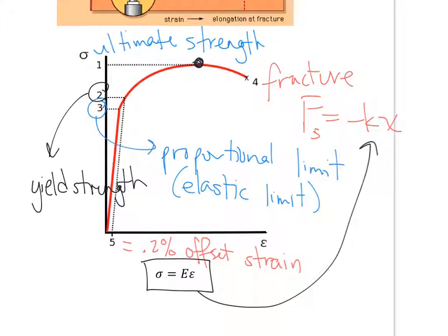So this, take a look. What do we say? This was the 0.2% off yield. So look, if we move this over to be a percentage, it's going to be 0.2%. This means that 0.2% of this has stretched. So again, 0.2% would be like 0.2 centimeters on a meter. So a specimen that's this small would be much less than even 0.2 centimeters.